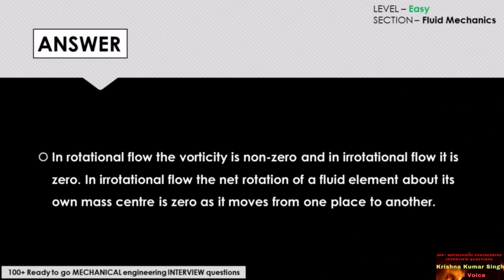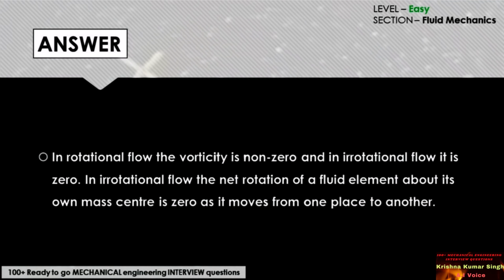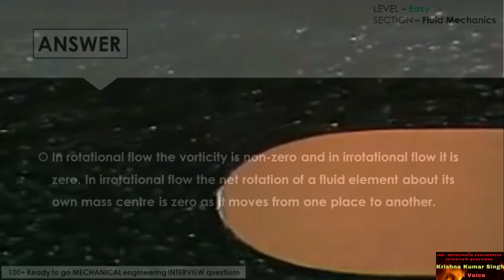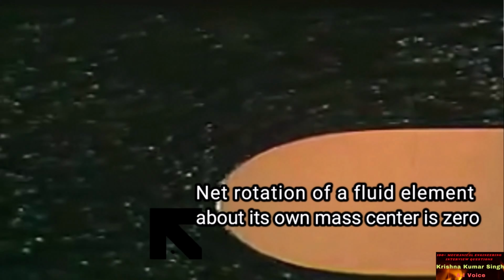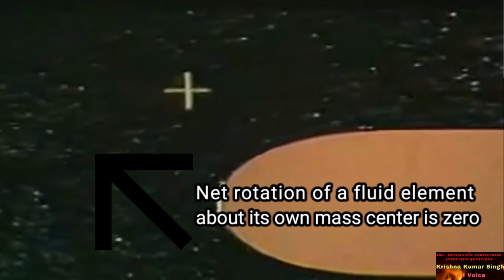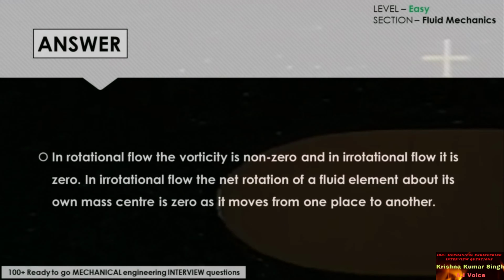The answer to this question would be, in rotational flow, the vorticity is non-zero, and in irrotational flow it is zero. In irrotational flow, the net rotation of a fluid element about its own mass center is zero as it moves from one place to another.